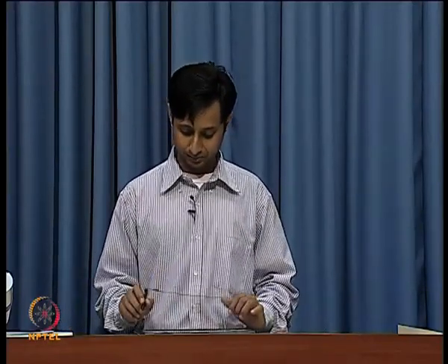Okay. So, this is called the input referred noise. You basically find the output noise and divide it by the gain squared. So, you find out the mean squared noise voltage at the output divided by the gain squared, that should give you the mean squared noise voltage at the input, which corresponds to the same mean squared noise voltage at the output. So, that is the input referred noise. This is the definition of input referred noise.